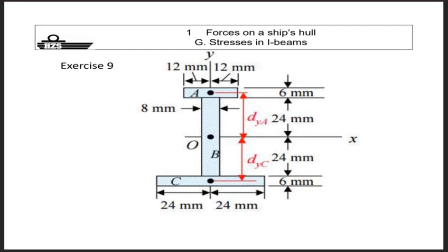And for that I-profile beam, you need to make a calculation for the Y, the area moment of inertia, but in this question they neglect the neutral axis. They just tell you we need to know the resistance against bending if bending takes place around the line X here, this line. Know that in the future, when you look at two vessels, we really need to know and calculate the I around the neutral axis. But it's just an example of how to calculate through the parallel axis theorem.